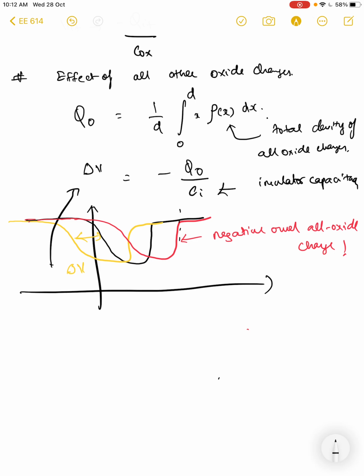So this is the threshold voltage, right? The voltage which is required to invert the channel, at what point to invert the channel, right? So Vt now depends upon the V flat band plus the oxide potential plus 2 psi b. This is the actual potential that is required to invert, plus the potential on the oxide charges,